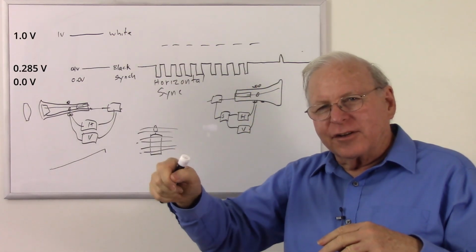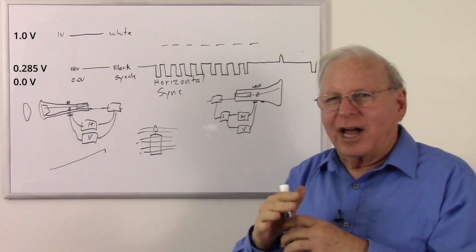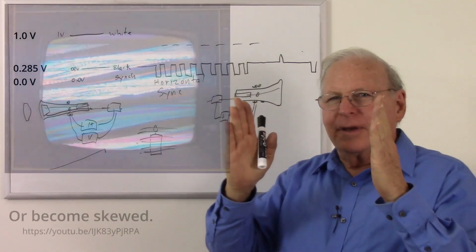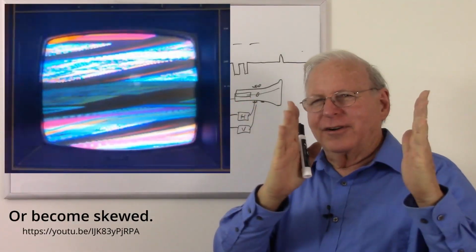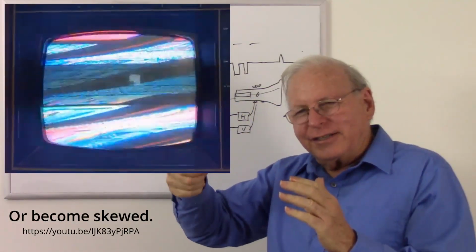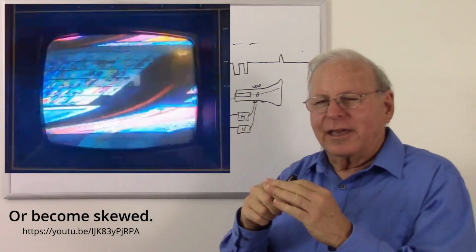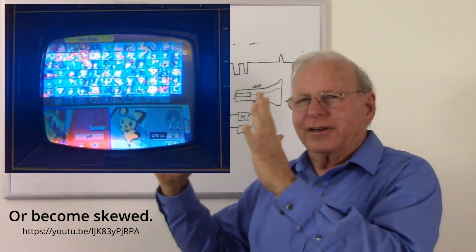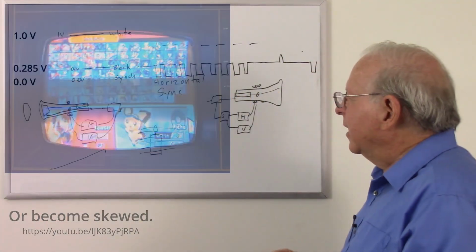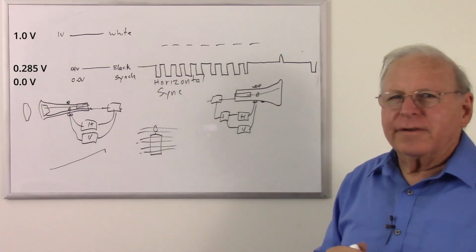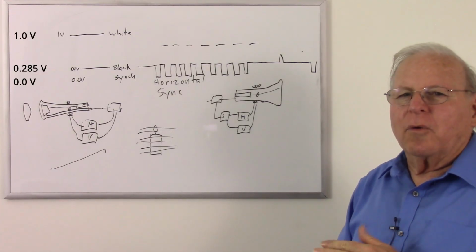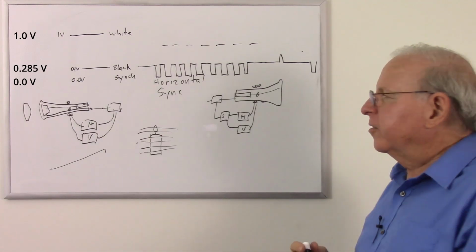You have to go and adjust the vertical hold to get that to stop and get that locked in. And then you also have the horizontal hold where the picture goes sideways. When you start going off to the side, you have to adjust that horizontal hold to get that to lock in, so you didn't see a black bar going across as your picture slid from right to left or left to right when they got out of sync. But toward the end of the analog TV's heyday, we had some systems that locked in so well that we didn't have to have those controls on the TV.